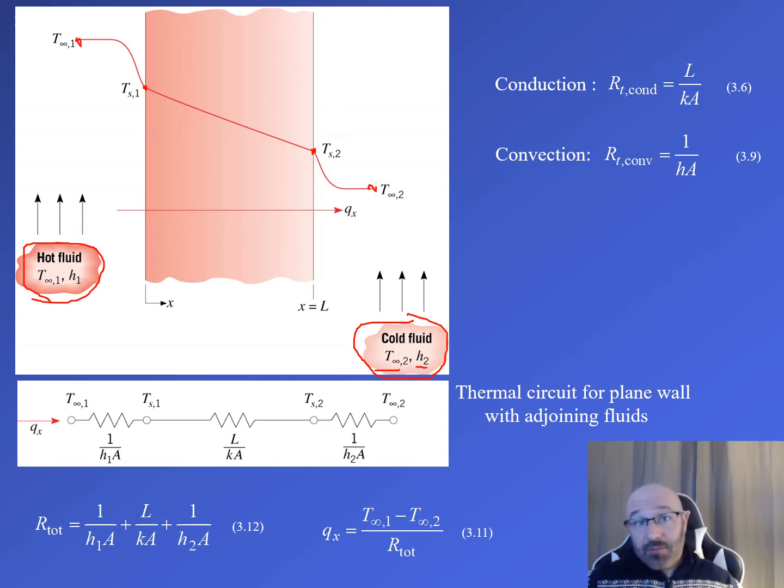So this is for temperature distribution. You think of this thermal circuit for temperature distribution. So we come over here and we're calculating our thermal resistance. This is a thermal circuit here. From this node here, I write a node down here. From this node at the surface, I draw a node down here. From this surface here, I write another node there. And from this one over here, I draw this other node right there. So now I've got all 4 of those, relating to those 4 temperatures from this initial diagram here, and I can begin to draw my thermal circuit.